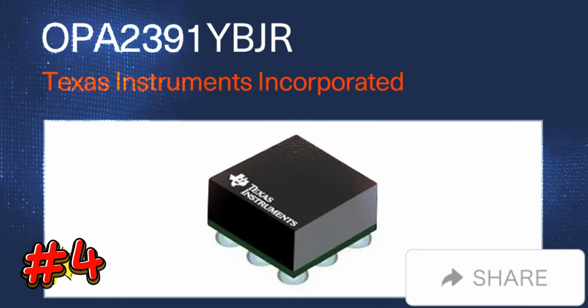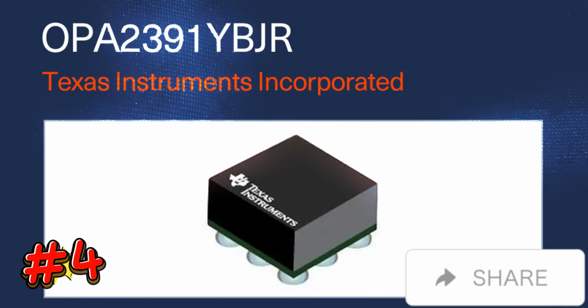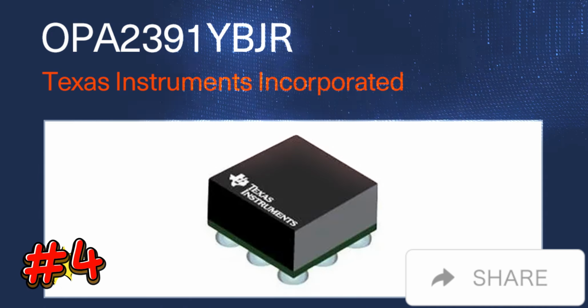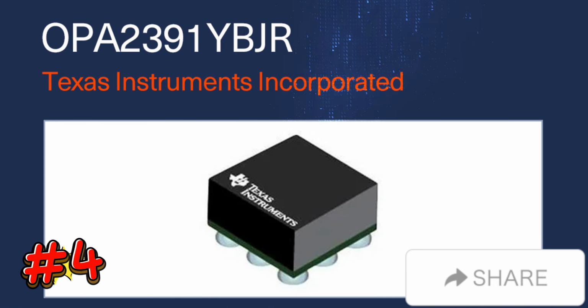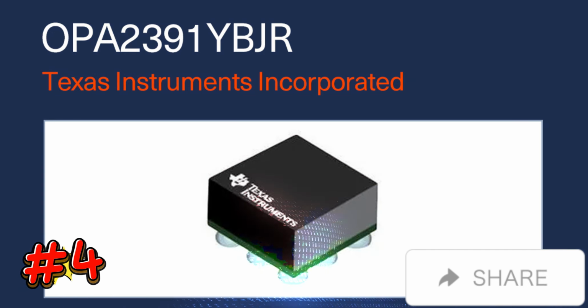And only 45 microvolts of offset maximum and 1.2 microvolts per degree Celsius of drift over temperature. This helps the op-amp maintain high precision in ratiometric and amperometric sensor front ends, which often have demanding low power requirements. It is an exceptional op-amp in high gain and low power applications.